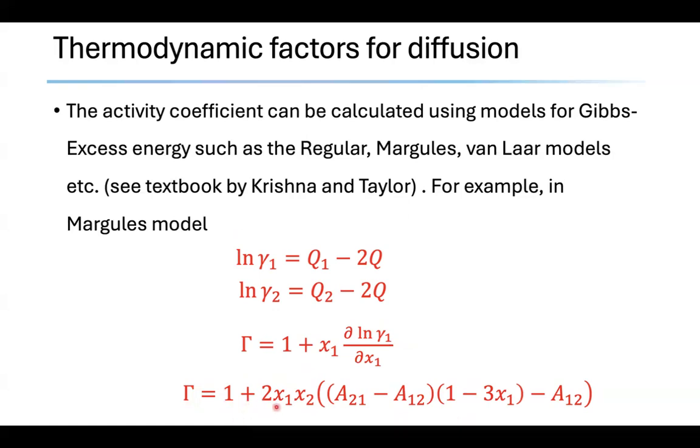Note that the thermodynamic factor depends on the mole fraction of component 1 and the constants A21 and A12. It is not a function of x2, at least explicitly, since x2 can be expressed in terms of x1 because this is a binary mixture.